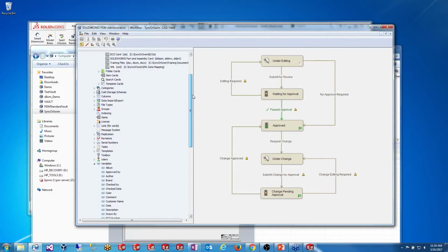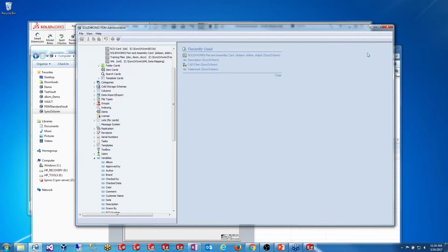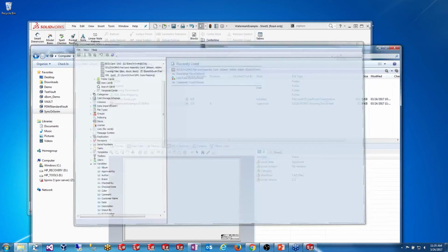And just like we did for the watermark, we're going to add an action. Oh, I'm sorry, we're not adding an action for our description because this is going to be entered manually into our drawing. If we wanted an action to be applied to this and have that custom property information of our model written to the title block of our drawing, we could add an action in our workflow, but in this case, just a manual kind of thing.